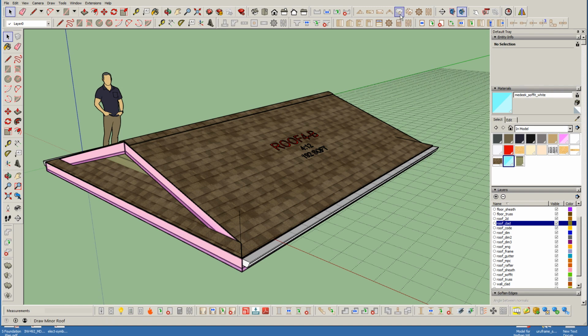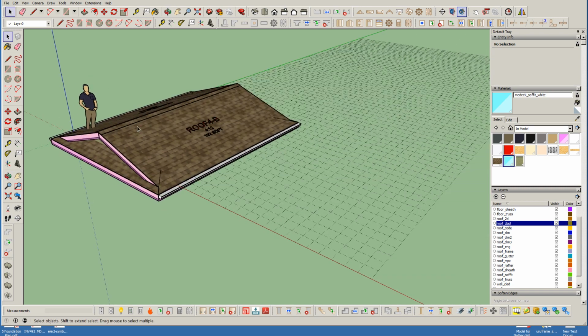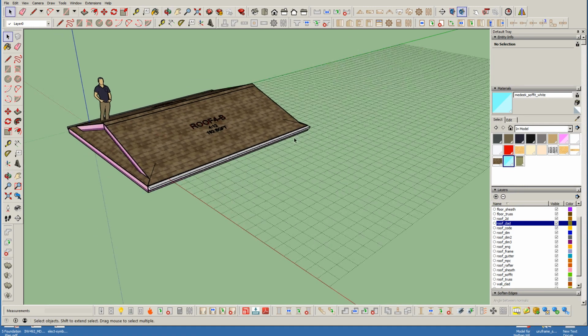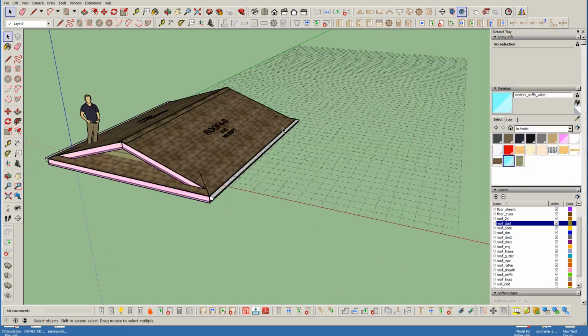So really, there's going to be two pieces to this: there's a complex roof, and then there's a secondary roof. The secondary roof concept is, you draw your primary roof like this, and of course it could be as complex as the primary, and then you can start adding pieces to it. You pick a couple points here, pick the plane of the roof, or just the roof assembly itself, and now boom, all of a sudden it connects that roof into that primary roof. So yeah, secondary roofs and complex roofs, that's the direction I'm going right now.